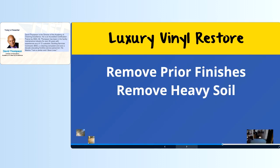Well, we've got problems in the environment out there in the marketplace. This is because people have been putting basic floor finish that's meant for VCT floors on their floor, and then they've used whatever disinfectant. And what we have is a chemical buildup. Because this is a non-porous floor, it's very hard for these floor finishes and products to actually stick. They're sitting on top of the floor. So what happens is it becomes just a big, soft, soily, gooey mess. I have more than my share of ones to restore.